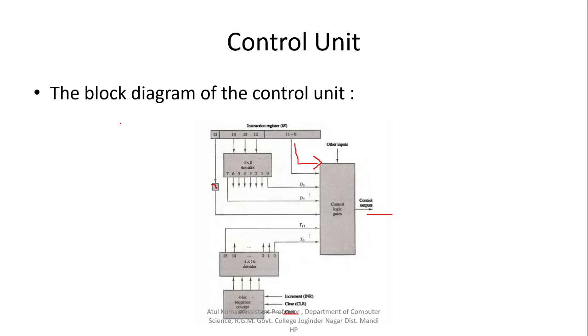During the second clock pulse, it is incremented to 1 and the timing signal T1 is produced as an output, and so on up to T15. After T15 the clear is activated and the sequence counter again returns back to its initial position 0.